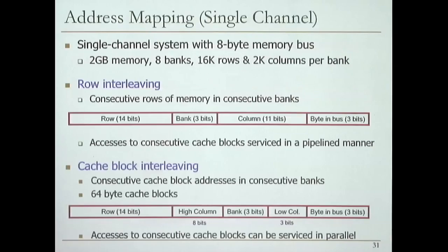If we go over here, these are the two major interleaving schemes. And if you use either of these, yes. And I can only access 8 bytes at once because of the bus. So I have 8 cycles for one cache block. And then if I pipeline this again, is it again 8 times those 8 cycles? Exactly. So for each cache block, you spend 8 cycles on the memory bus. OK. Yeah, that was it.